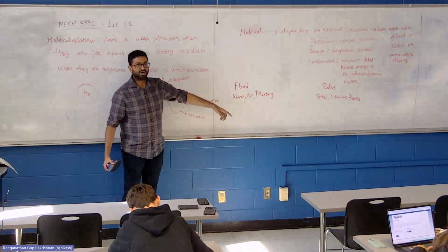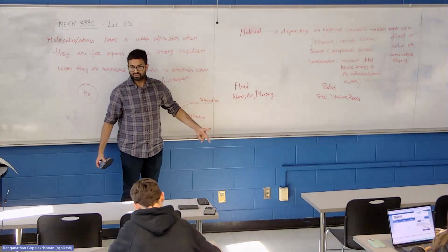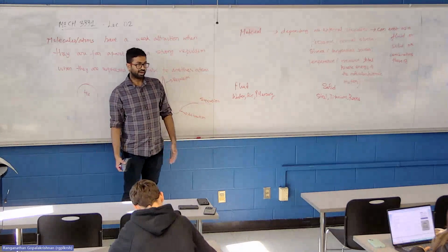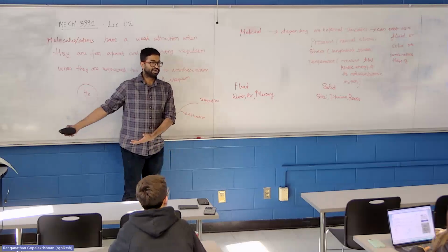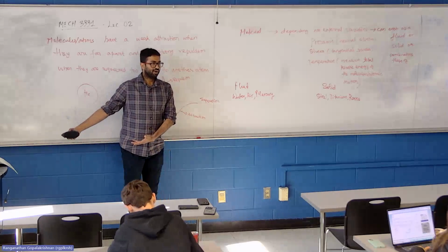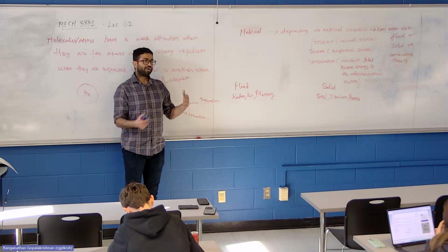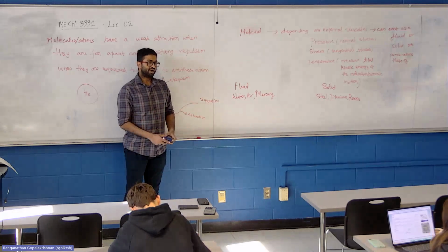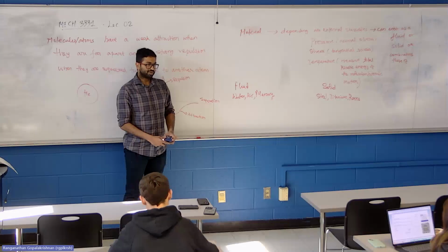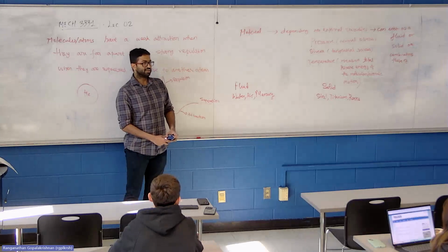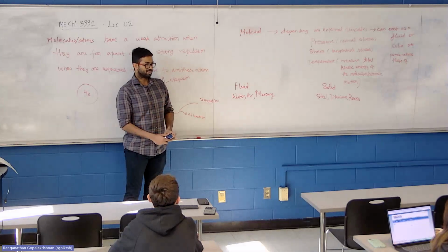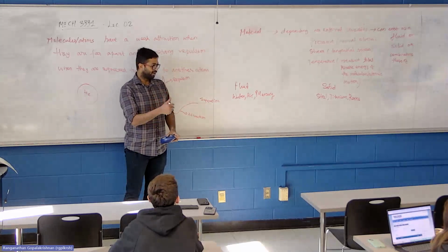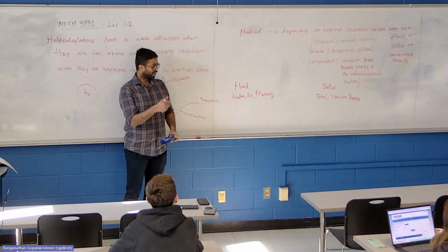And water, well, you have to ask me the question. When you say water, what pressure and temperature are you talking about? Are you talking about regular room temperature, or am I talking about temperature that is in the North Pole, or am I talking about the conditions inside a pressure cooker? Do you know what's the boiling point of water inside a pressure cooker? Anybody? Is it 100 degrees Celsius or more than 100 degrees Celsius? It's more than. When pressure increases, the boiling point goes up. When pressure decreases, boiling point comes down.